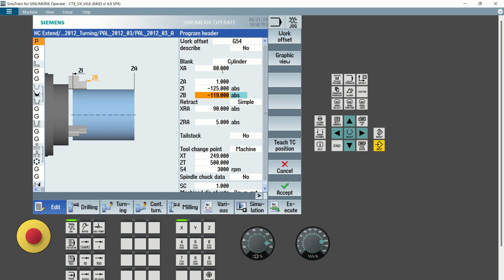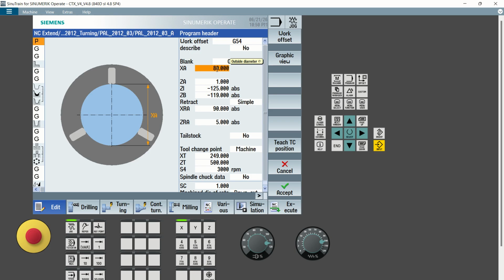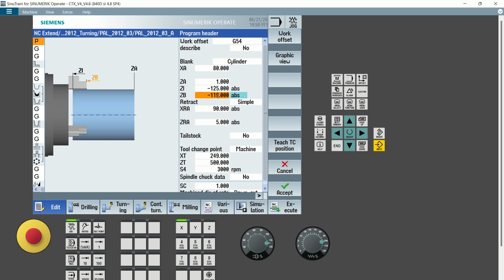So you need to know how to calculate the overhang. You take the maximum diameter, that is 80, times 1.4, to see if it will wobble or not. So 80 times 1.414, you get 113. So I'm within 119, so there's no wobbling here.